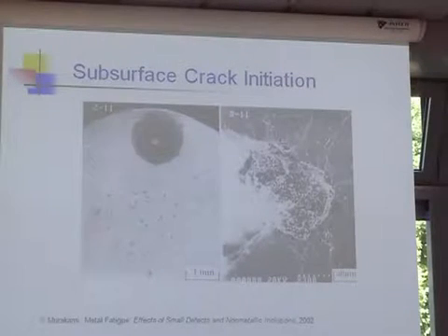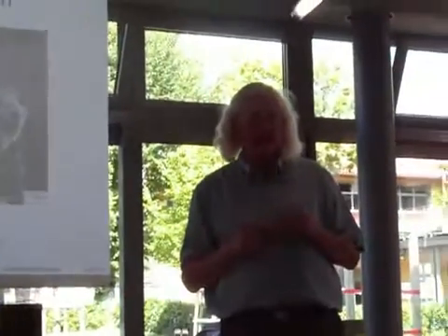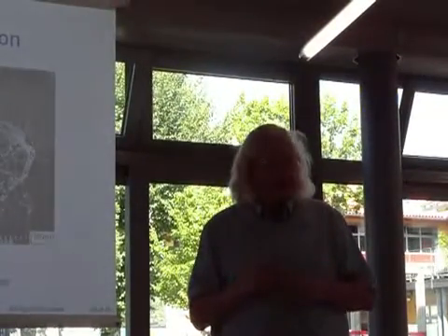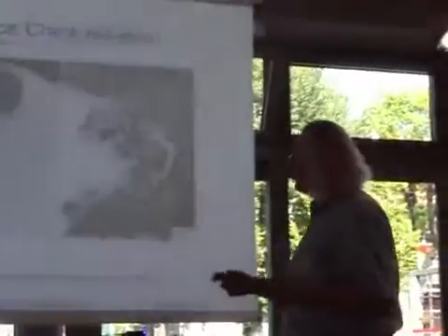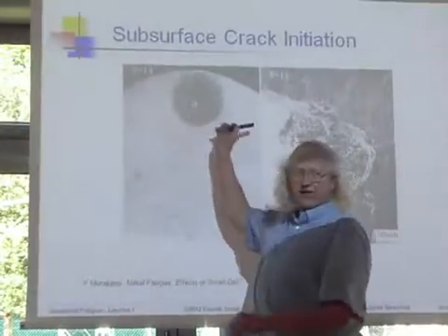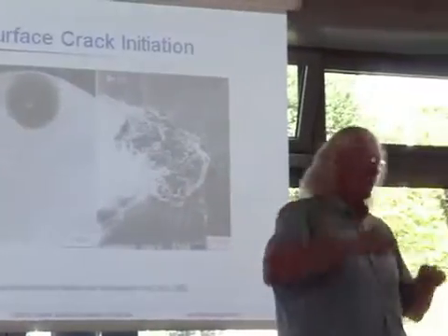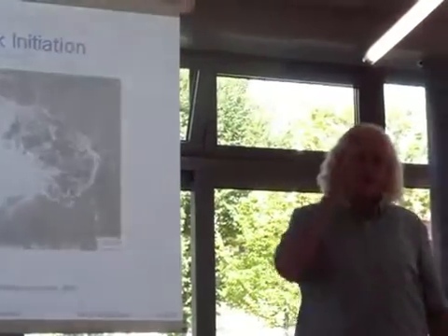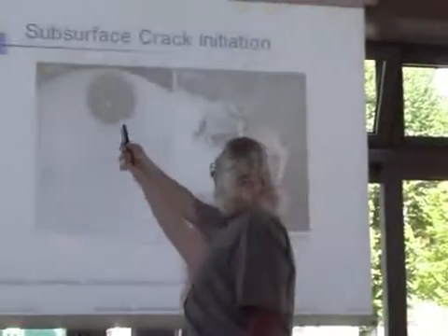strength, and it was a Japanese bearing manufacturer, and he showed the progression of steel over the last 30 or 40 years, and he put up a slide. You can imagine that the first slide he put up, he said, here's the inclusion. You can imagine it was about that size on the slide. And he said, here's what we sold in 1980, and he gave the fatigue limit. And then he said, here's what we sold in 1990,